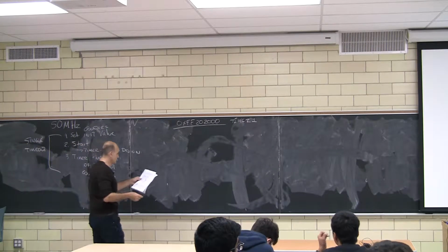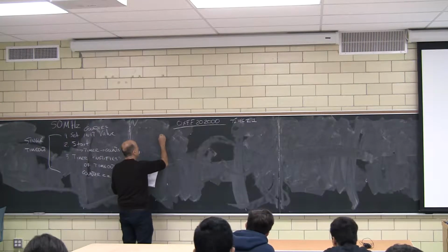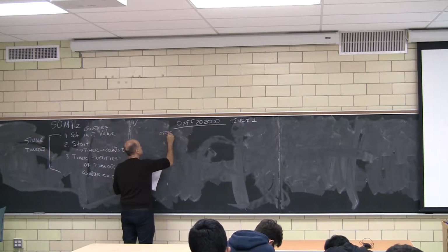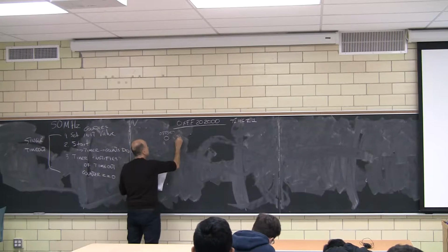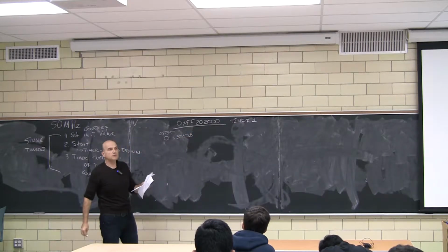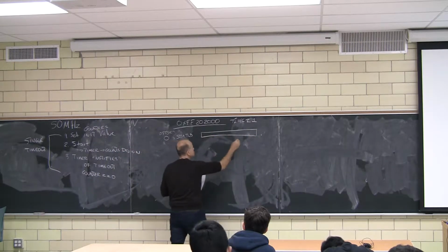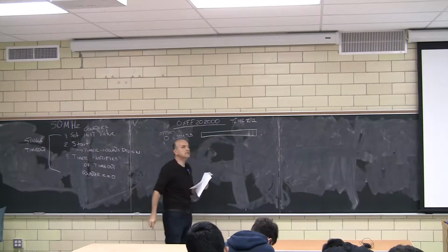The ones that we're going to be discussing for the time being are the first 4, which is at offset 0, you have the status register. All of them are 32-bit registers. The status one really has just 2 useful bits for us, and they're both indicators.